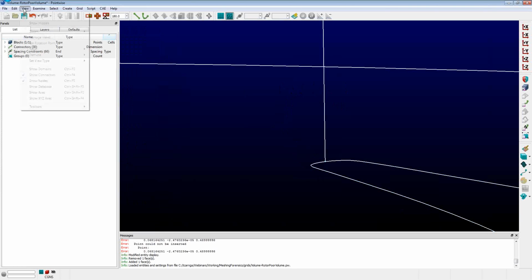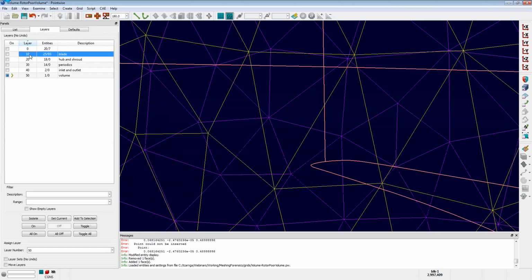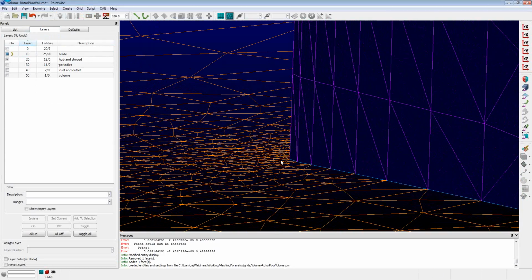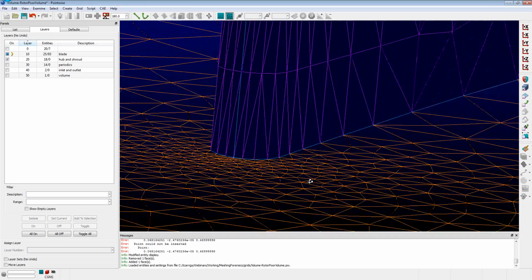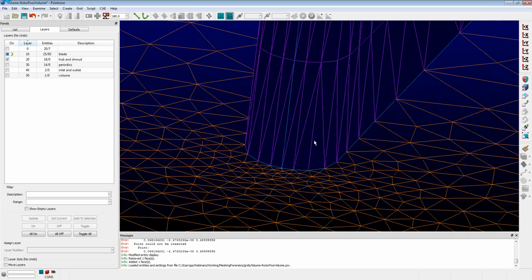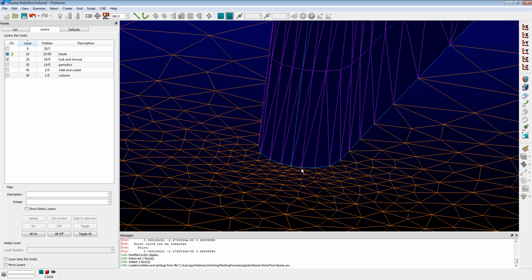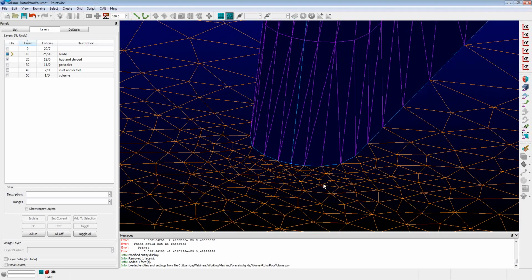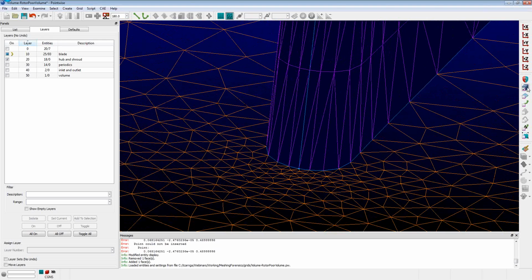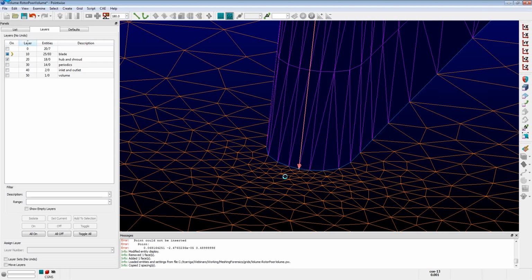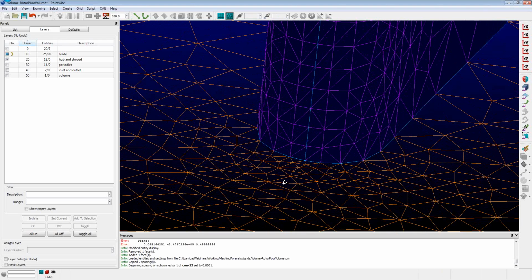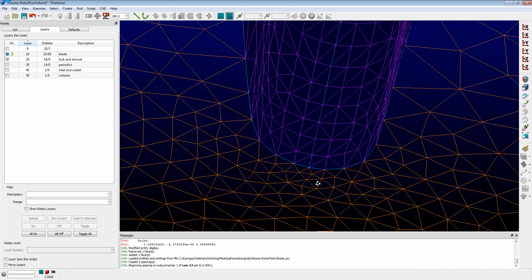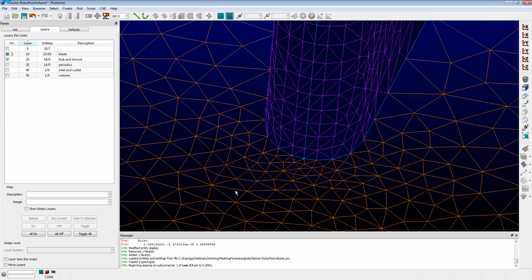And if I turn on the view of the domains, I'm just going to isolate the blade, the hub, and the shroud. I think I know what's going on back here. If I rotate around, it looks like we just have a mismatch in spacings at this connector junction. So we've got these really tall cells next to some really small elements causing those large volume ratios and then the stop points during the extrusion. So for unstructured meshes, we recommend that at these connector junctions you have about the same spacing. So that's what I'm doing. I just copied the spacing and now I'm pasting it to that vertical connector. So now we have cell sizes that are roughly equivalent in this region at this connector junction, eliminating those large volume ratios and those stopped points.